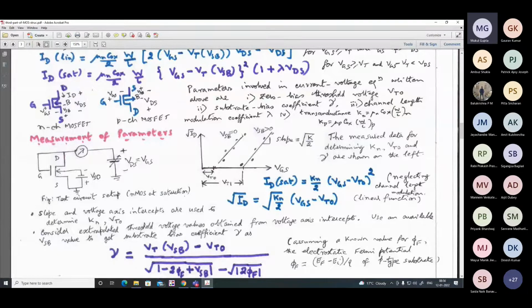Continuous means you mean to say suppose VSB equal to 0 and VDS can go. You see how much current is allowed to pass for a transistor, that is provided by the manufacturer. Say it is given as 5 milliampere or 10 milliampere. So we have to see that drain current does not exceed that limit. So we have to stop at some point of the drain to source potential.